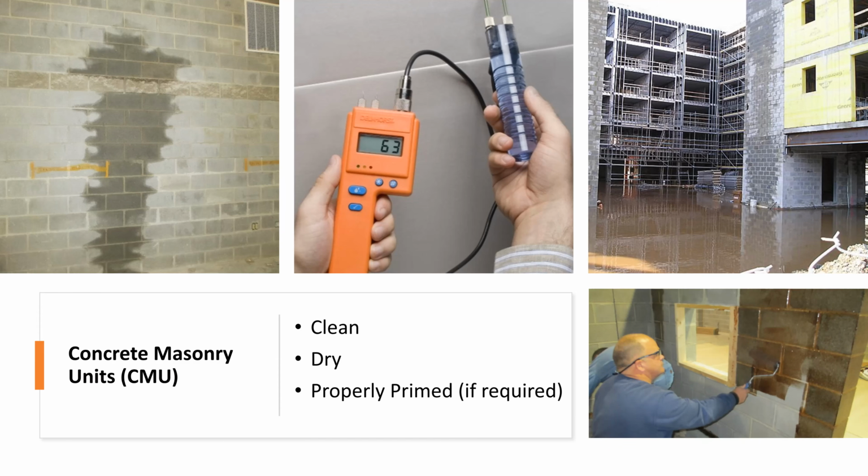It helps lock in some of the dirt and debris. It soaks into those pores, and then you're actually adhering to the primer itself. So you've got concrete masonry unit with these pores, you've got this primer that digs in and locks in, and then you're applying the air barrier to it, okay?